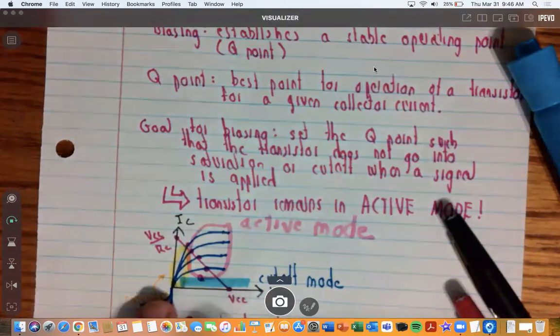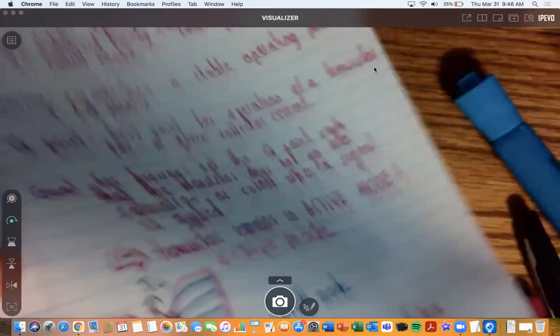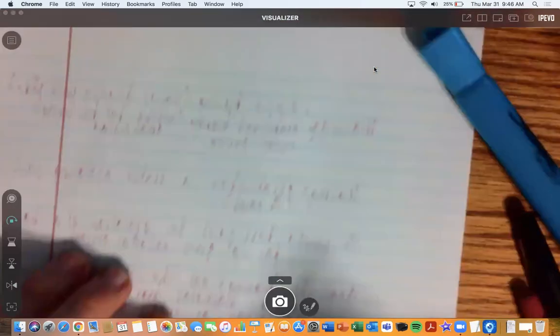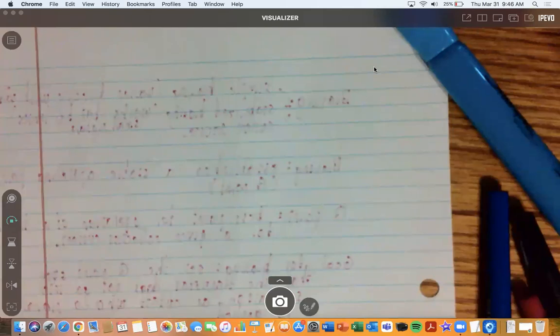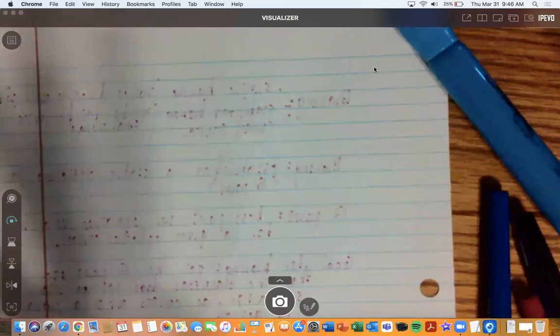We just don't use it a lot because a transistor is not normally meant to be in inverted mode. Because if you're in inverted mode, it's just going to be a lot less effective. It's basically your NPN transistor, and you're trying to make it function almost like a PNP. And why would you do that? You just use a PNP transistor. If you're using the opposite charge carriers to flow, you should just use the opposite type of transistor. You shouldn't force one type to act like another one.